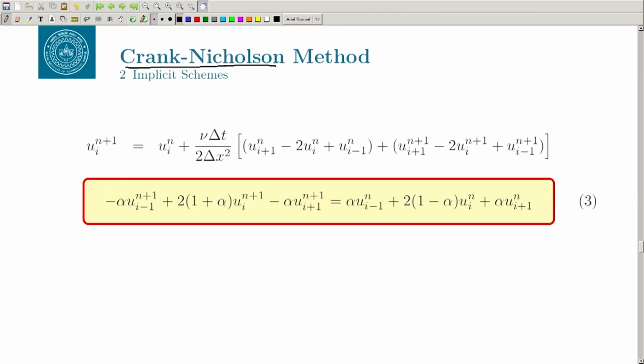So, the implicit problem, as I told you earlier also, is very useful when you want to just get the mean flow. For example, in the RANS simulation, Reynolds averaged Navier-Stokes simulation. So, for example, you started with some initial condition, okay. This is your first point and you want to go here, okay. So, let us say you use the explicit approach, this probably goes like this, okay. This is your explicit approach, where you are honoring the accuracy at every time step and getting from this point to this point, okay.